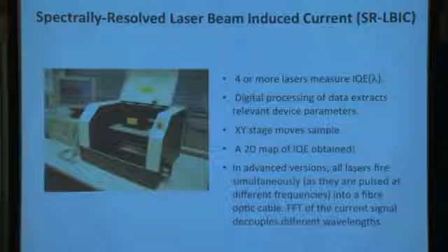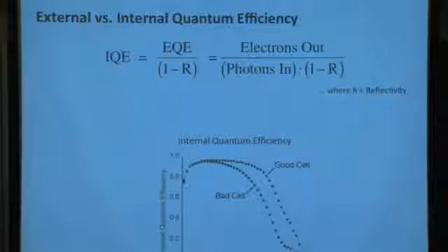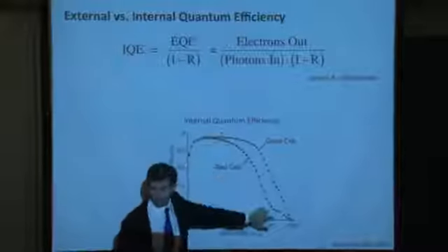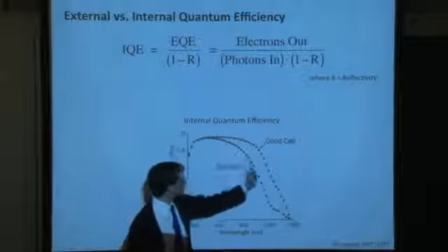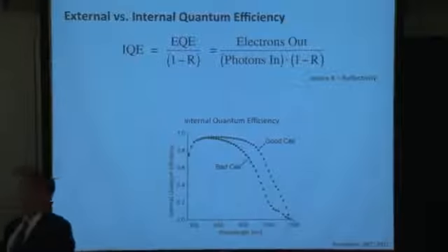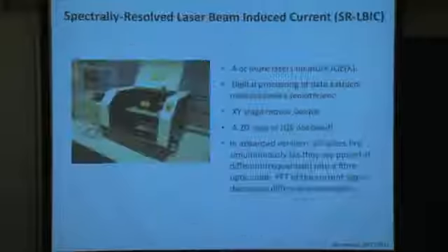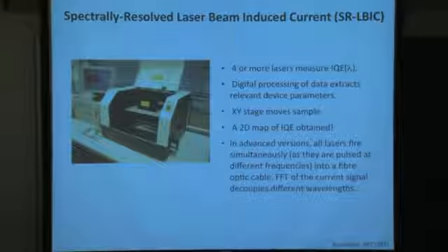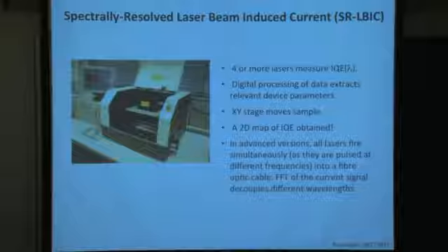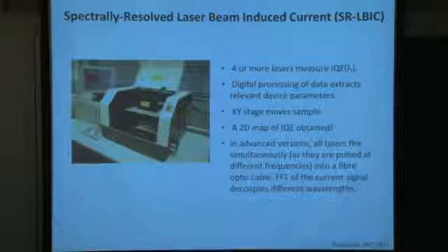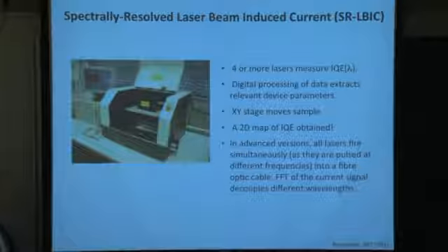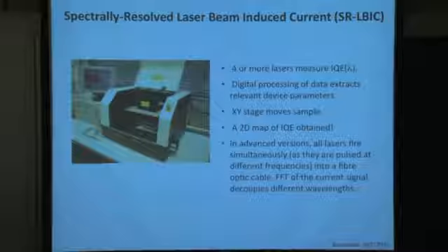Now, you need a few different wavelengths of light to really flesh out this curve, to determine the minority carrier diffusion length from this curve. And so the laser light is typically chosen at very auspicious wavelengths to maximize utility in this particular type of evaluation. So we usually have four, minimum three. You can always fit a line through 2 data points, so minimum 3 laser wavelengths, and usually about 4 or more to process the quantum efficiency as a function of position.